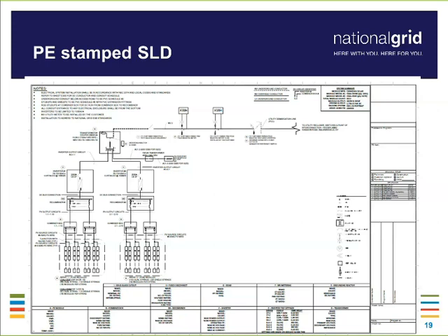The key components that are of interest here are going to be the point of interconnection. On this drawing, it shows a dashed line. Typically, with an overhead system like the one shown, that demarcation is going to be at the fastening point to the three-phase gang-operated switch provided by the customer. So that's what's shown in this case. Showing that customer switch is important. And if it's a gang-operated switch with a fused service arrangement like this one, we'd expect to see that. Or if it was an overhead arrangement with a recloser, or whatever the overhead service protection would be, that would be a requirement to show.